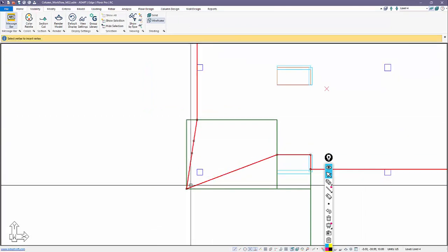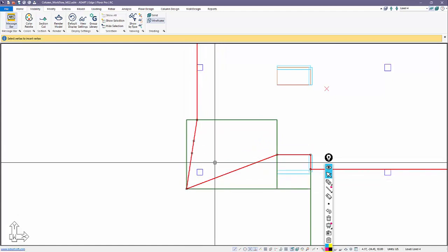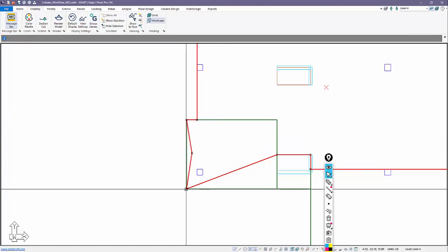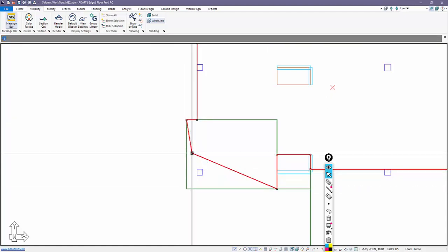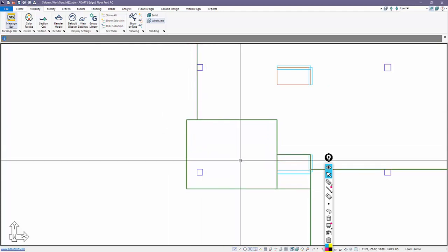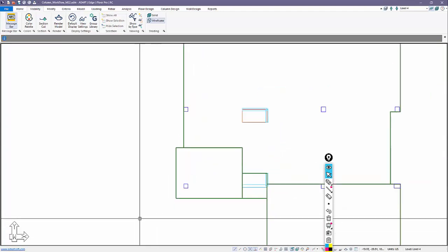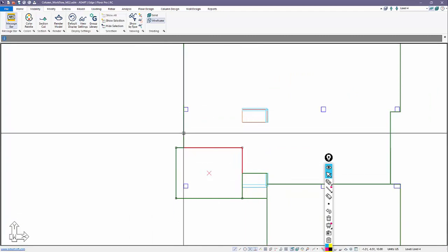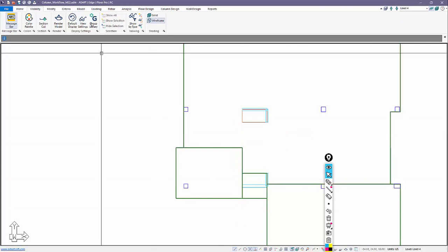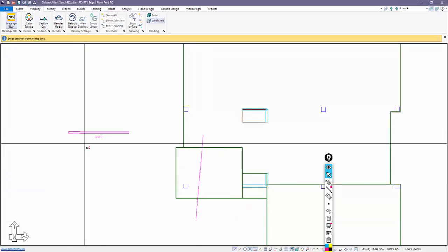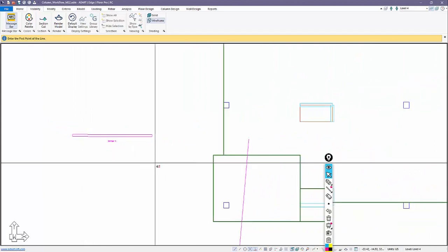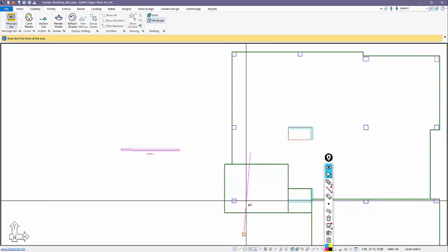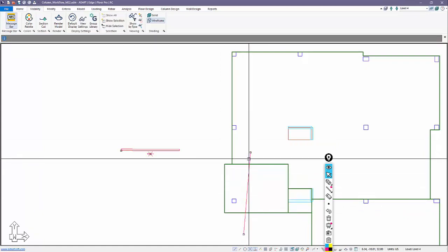I'm going to add point 1 and just 2 points is all we need. So we'll come back and just reassign the location of these points. This one I'll slide over, and this one I'll slide here. So we've nested one slab on top of the other. We still are going to have an offset because this slab that's offset is actually contained within this larger slab that now encompasses it. So if we make a section cut through here, we still have the geometry that we want. It's just now, in terms of column design, the program recognizes that it is touching a slab that is no longer offset. This is, again, the workaround.